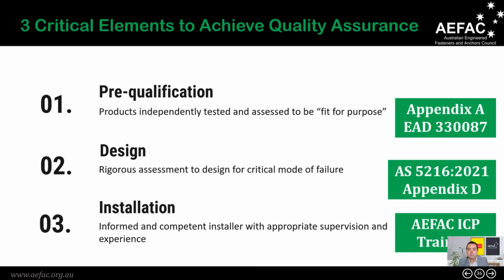The objective of this EAD or Appendix A is to ensure that post-installed reinforcing bar performs at least similar to or better than cast-in rebar. The performance should be compared in terms of strength and displacement behavior.